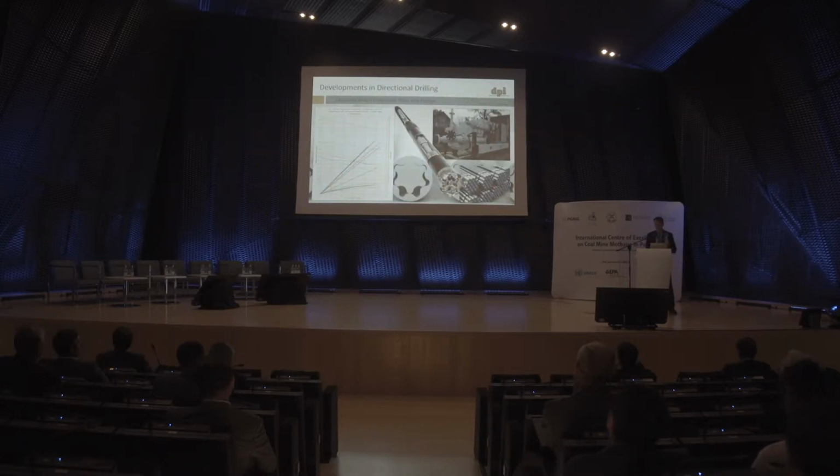The second part of the equipment side is really the downhole directional equipment, and developing that equipment to be able to match with the extended reach drills. So essentially extended reach directional drilling tools. And what we're talking about is we've had to increase the capacity of our fluid pumps. We've had to increase the capacity of our downhole motors, using larger diameter downhole motors as well.